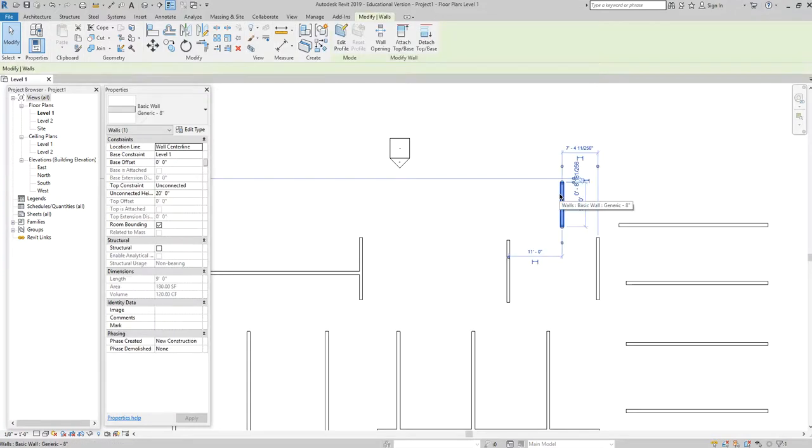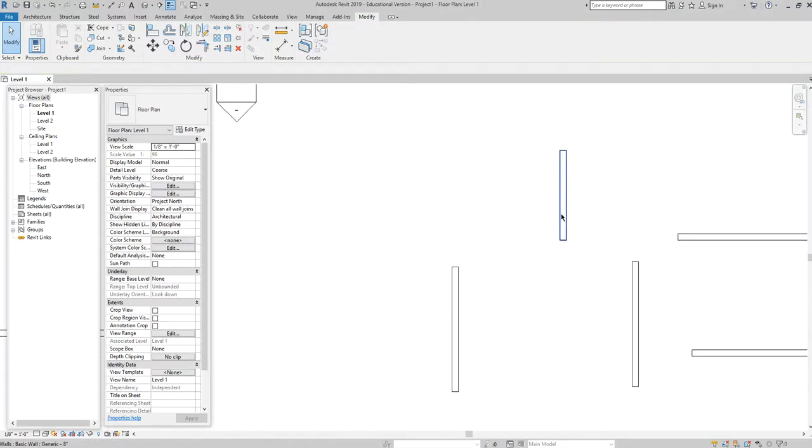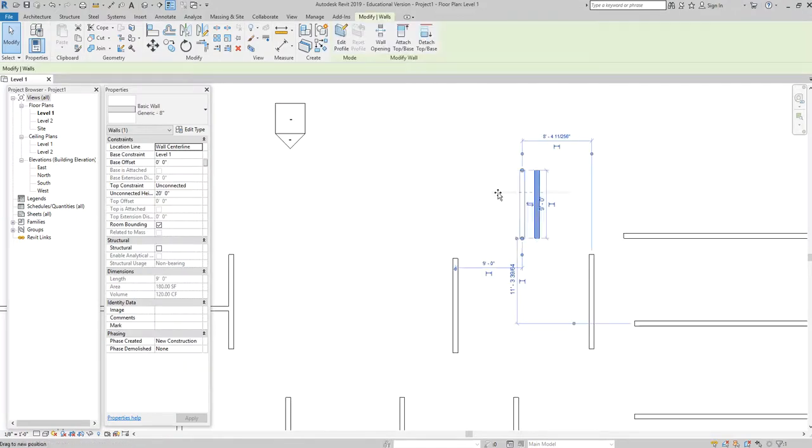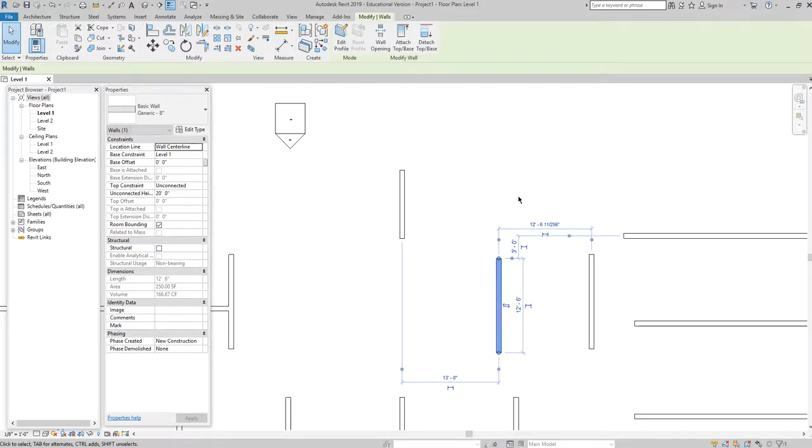And I would assume it's probably something like this where they were trying to move a piece of annotation, they were dragging a wall or a toilet, and they accidentally grabbed the slab. So be careful with the drag command until you feel responsible with it or know what you're doing. But that is a good way. You'll see me using it a lot. But even now and again, I do pick things that I shouldn't.